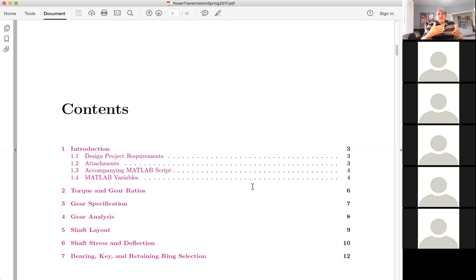And then we would have to do the deflection. So we have done the calculations for the moments. Then we would have to do the deflections. And for the deflections, we would like to use a MATLAB code that I posted online. And the reason is that the analytical formulas that we developed are for uniform dimensions of the shaft, so the shaft dimensions do not change as a function of location.